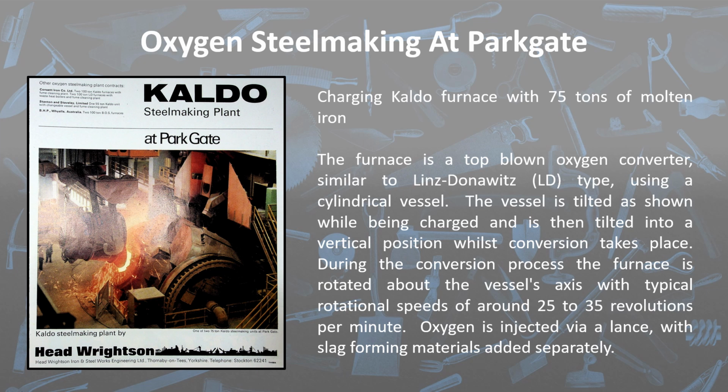During the conversion process, the furnaces rotated about the vessel's axis with typical rotational speeds of between 25 to 35 revolutions per minute. Oxygen was injected via a lance with slag-forming materials added separately. Unfortunately, due to severe mechanical engineering problems, the process was not a success and was decommissioned when British Steel was